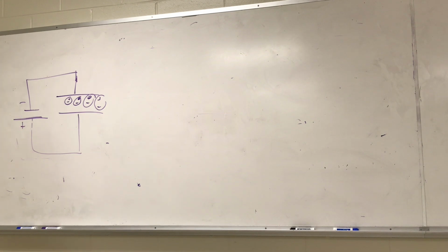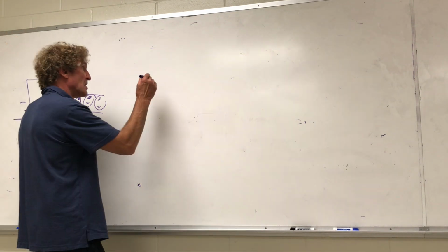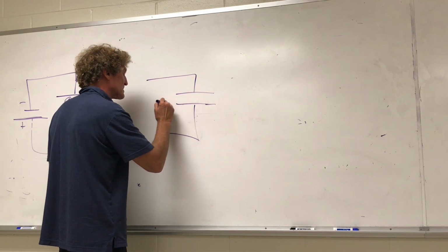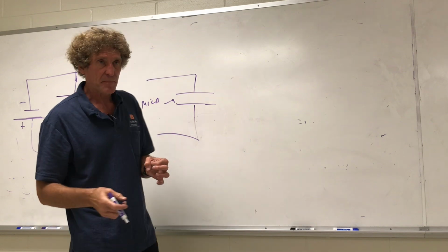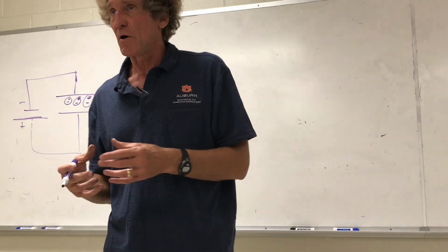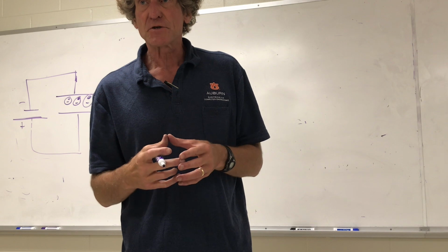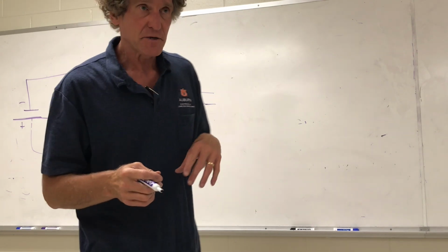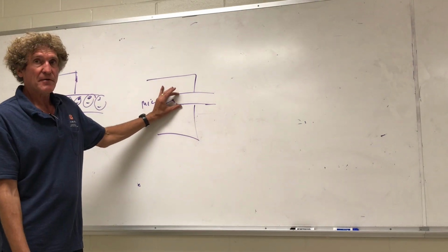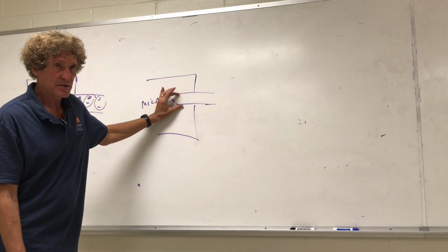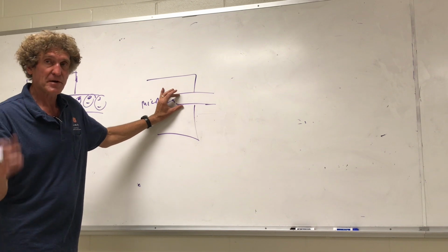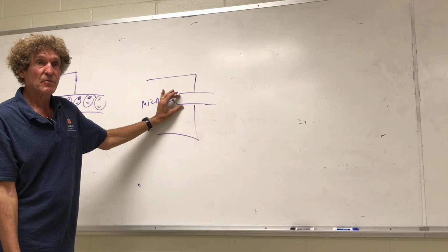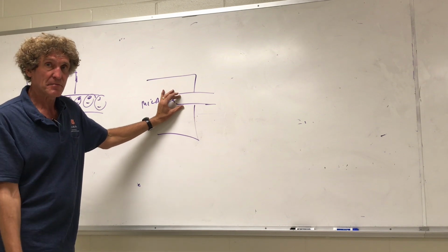That's an electrolytic capacitor. The other kinds are the ones where the dielectric is solid, like mica, for instance. These are the little disc capacitors, but they can be large or small, and they generally don't store as much energy for a given volume of space. But something about these two is you can have a fairly high breakdown potential. Anybody remember what the breakdown potential of air is in terms of volts per meter? What electric field would cause an arc to begin? Gannon, do you remember that?